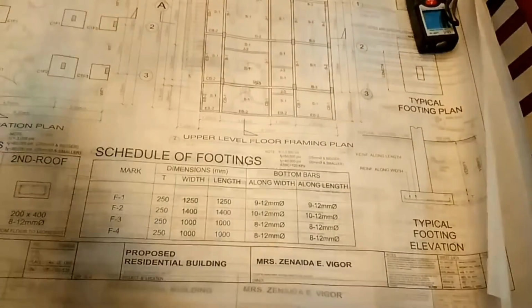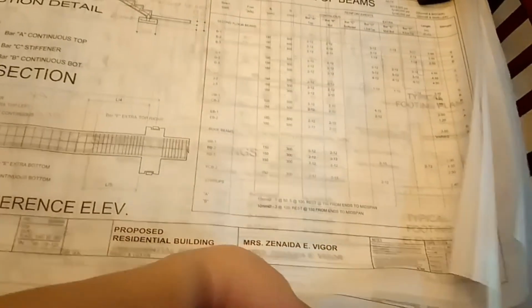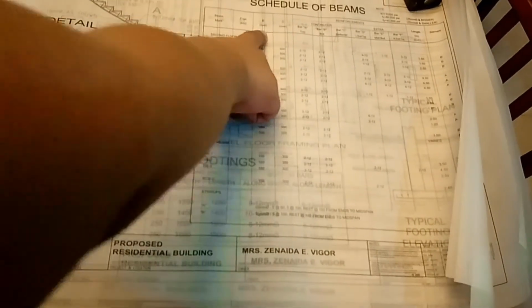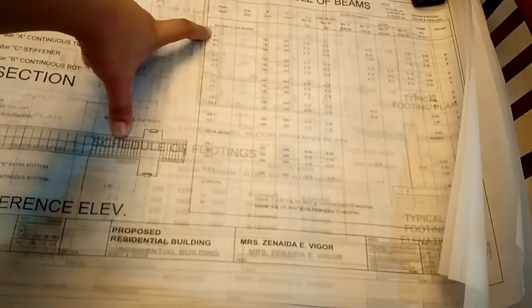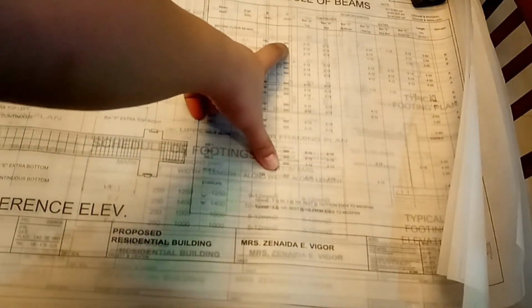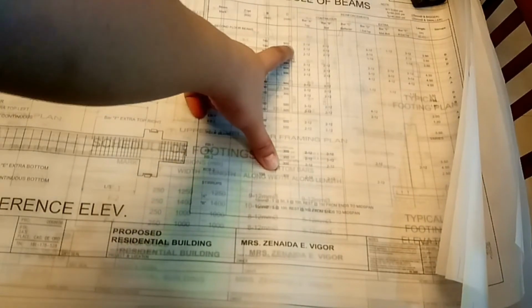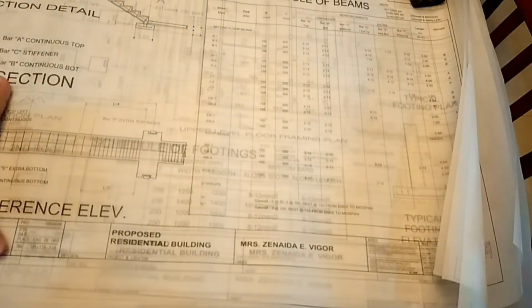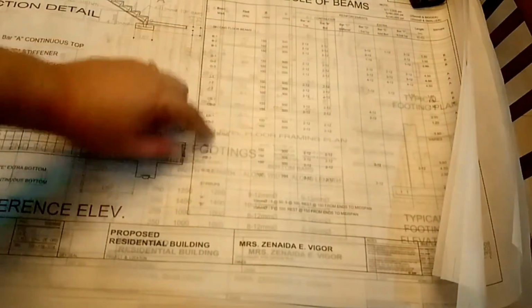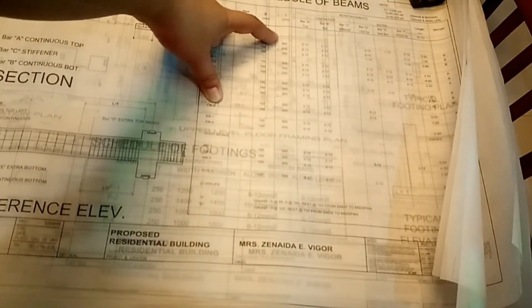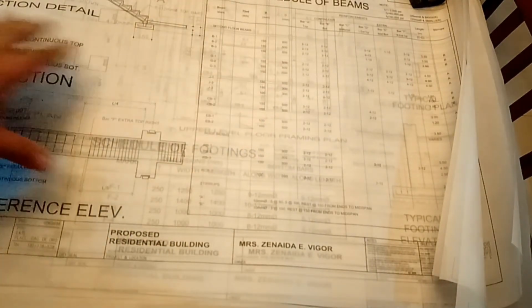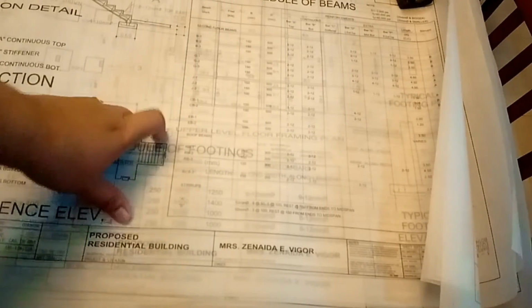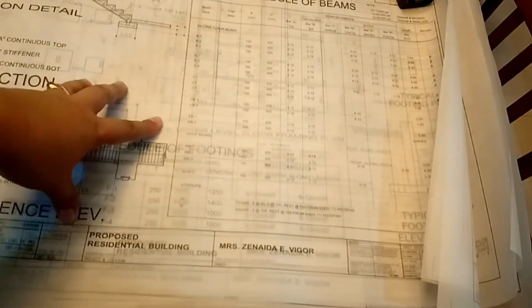Okay, so let me show you one more thing. This is also important for you to see. It's what you call the schedule of beams. Okay, so all the beams and their sizes, they are written here. For example, it's B1, the size of the beam is 150, then the depth is 0.5. Okay, this is 150 mm by 500 mm. In meters, it's 0.15 by 0.5. Okay, so do the schedule of beams. All you have to do is write down the beam mark, then the sizes. Okay, then you write also the reinforcements. When you do this in the actual class, you'll have to coordinate with your structural engineer.